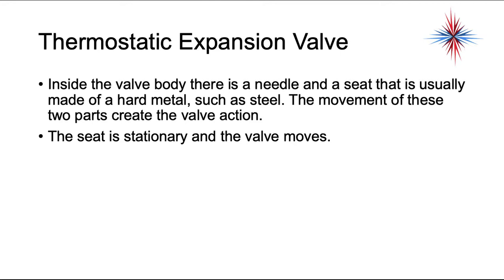Inside the valve body of a TXV, there's a needle and a seat that is usually made of a hard metal such as steel. The movement of these two parts creates the valve action. The seat is stationary and the needle moves as the valve.